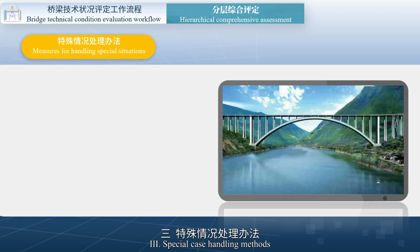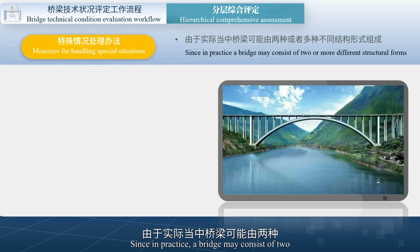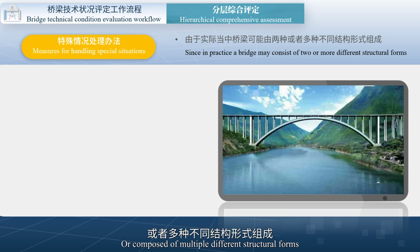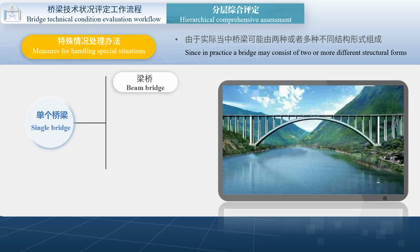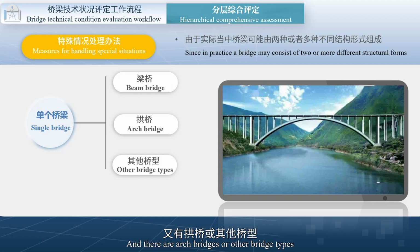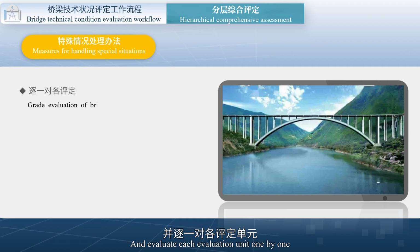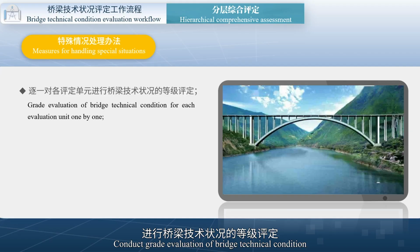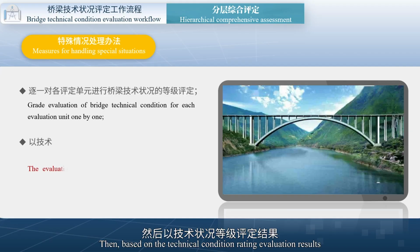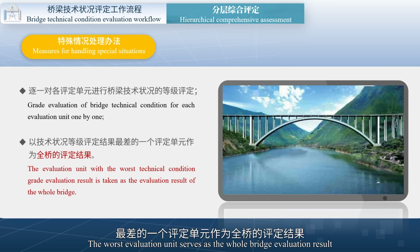3. Special case handling methods. Since in practice, a bridge may be composed of multiple different structural forms. When a single bridge includes an existing beam bridge, and there are arch bridges or other bridge types, the bridge can be divided into two units, and evaluate each evaluation unit one by one. Conduct grade evaluation of bridge technical condition. Then, based on the technical condition rating evaluation results, the worst evaluation unit serves as the whole bridge evaluation result.